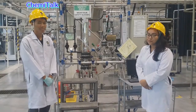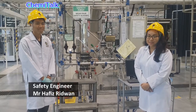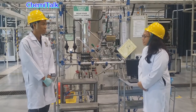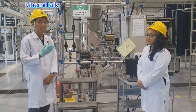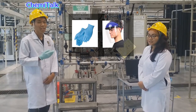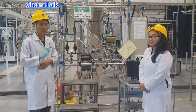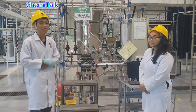Last but not least, we have our invited guest, Mr. Hafiz Ridwan, who is the safety engineer of the chemical industries. Hello, Mr. Hafiz. I have seen that the process involves ethanol. May I know what are the insights to handle this material safely? Okay, so firstly we need to wear gloves, as ethanol is irritating to the skin if it is exposed in large amounts. Also, it is recommended to wear a face mask because it is dangerous to inhale. And also to note is that we have to avoid sparks or flames because ethanol is highly flammable.